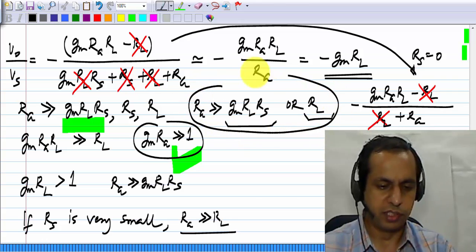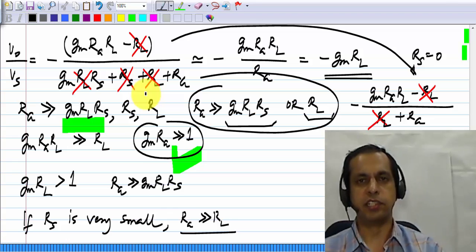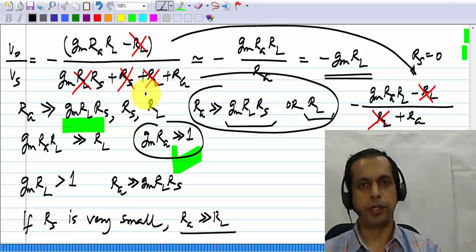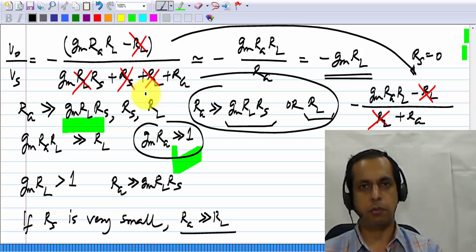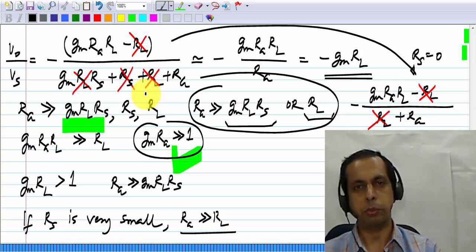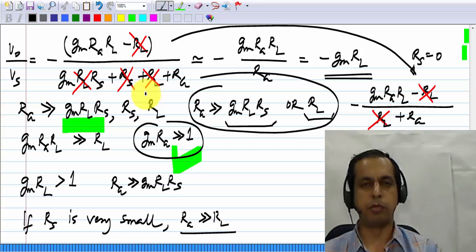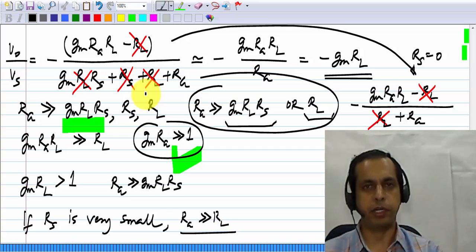So once this condition is satisfied, you will have the behavior of a common source amplifier, although there is a resistance between drain and gate. So that's the constraint on RG, and this is a very common situation in circuits. You want the element to be significant for some picture, let's say DC or AC picture, and insignificant for the other one. And what you have are constraints. Remember, you don't get from this analysis that RG should be equal to something. RG has to be much more than something, and you have to choose something much larger than that. And just like I mentioned for the capacitor, you could choose, let's say, 10 times or 100 times more and be done with it.